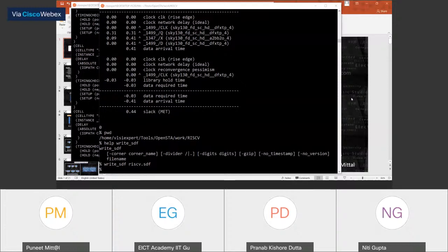Yes, Naveen was asking about an industrial tool: when we do synthesis, we read only .lib, .v, and SDC, and we generate a netlist. So the netlist is the same .v, SDF, new SDC file. We never read an SDF file during synthesis, but we use SDF and SDC files from the synthesis level to post layout.